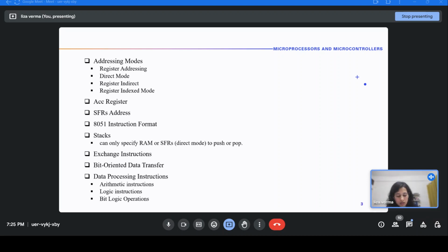And what is the difference between the instruction when you want to move data or you want to move from an address, since we have 8-bit addresses here? How do you differentiate between data and the address location in the instruction? If we want to specify data, then we have to put a hash in front of it.